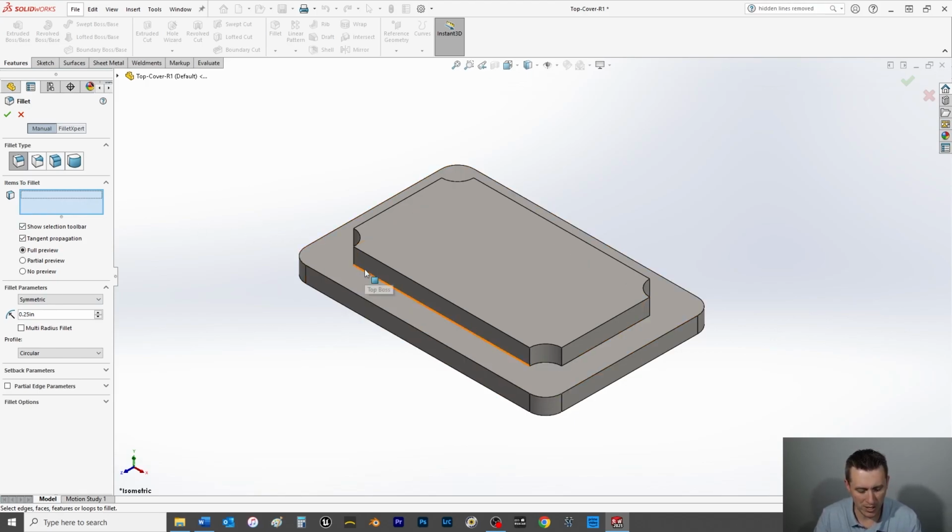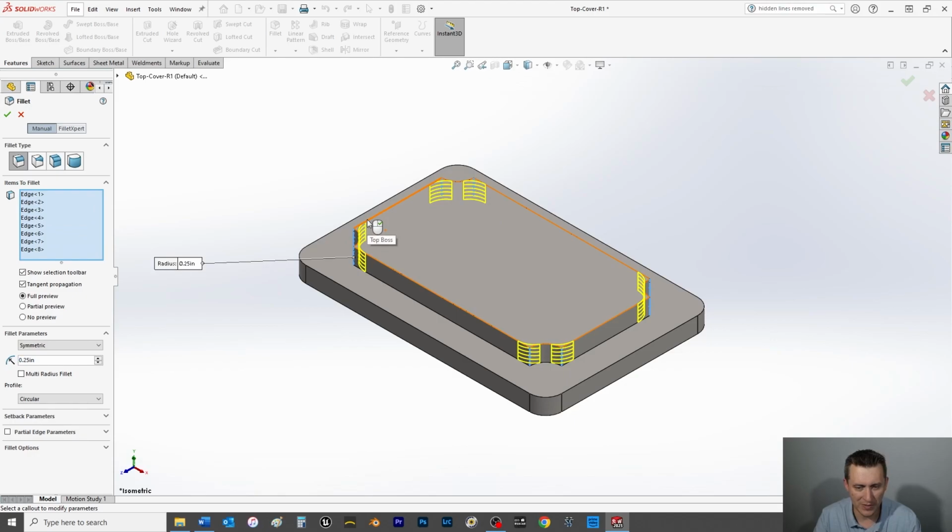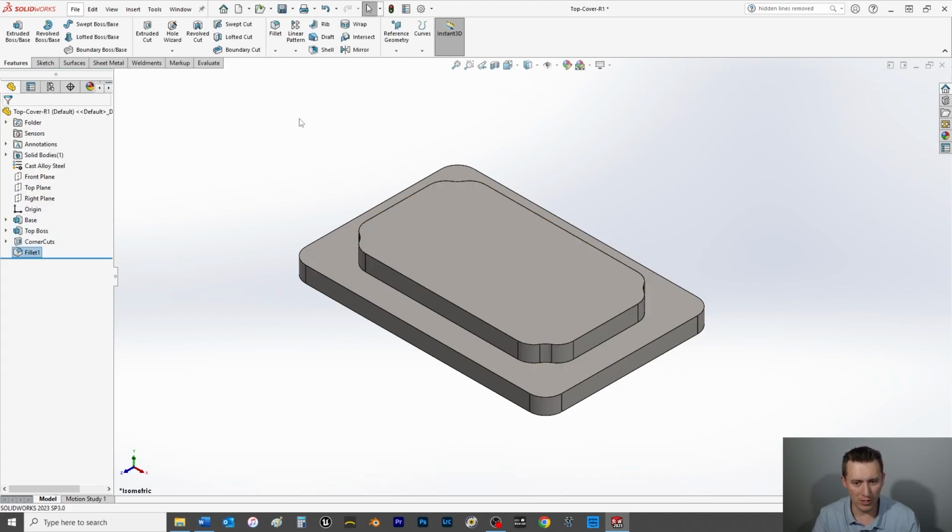And here, you can use the G command on the shortcut of the keyboard to zoom in to make a precise selection of this line here. Now notice this pop-up here, we want to do connect to end loop, 7 edges. That is a high-speed way of doing it instead of individually selecting every single one of those. And then we'll click OK, hit Control S again, saving often.